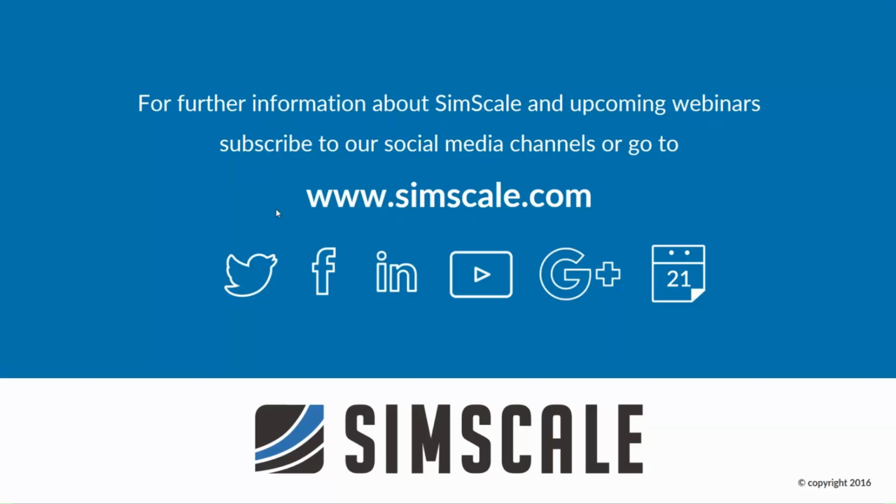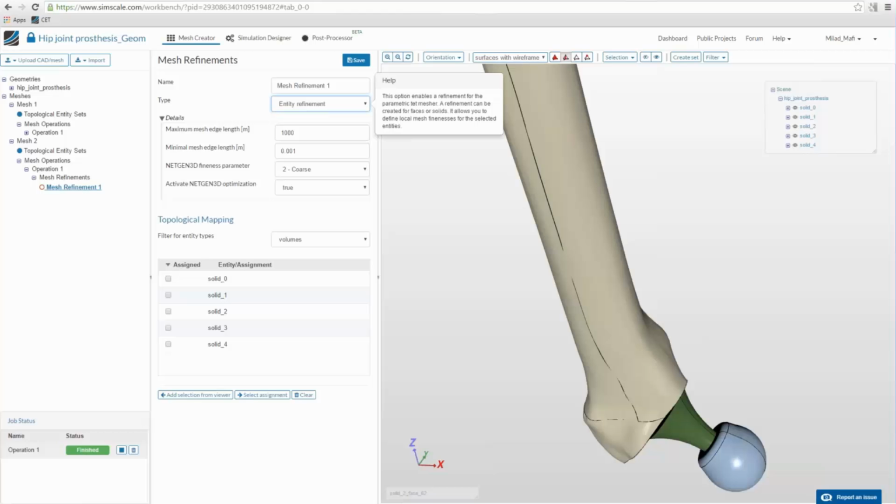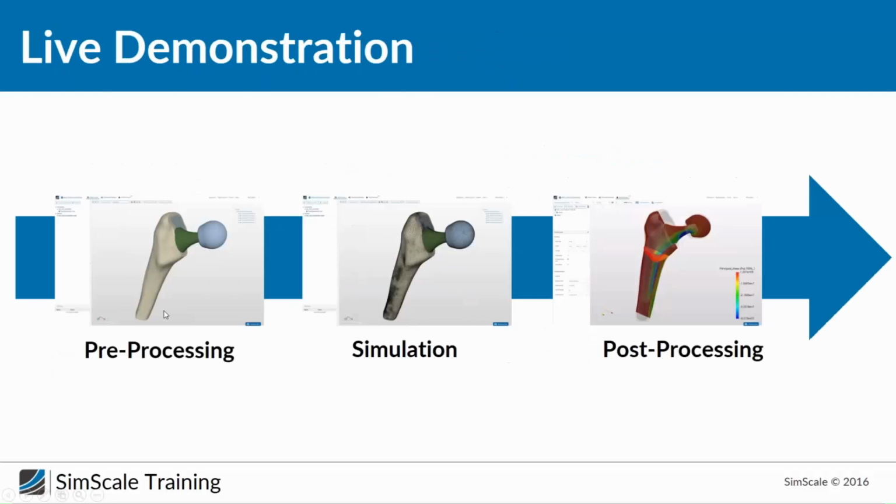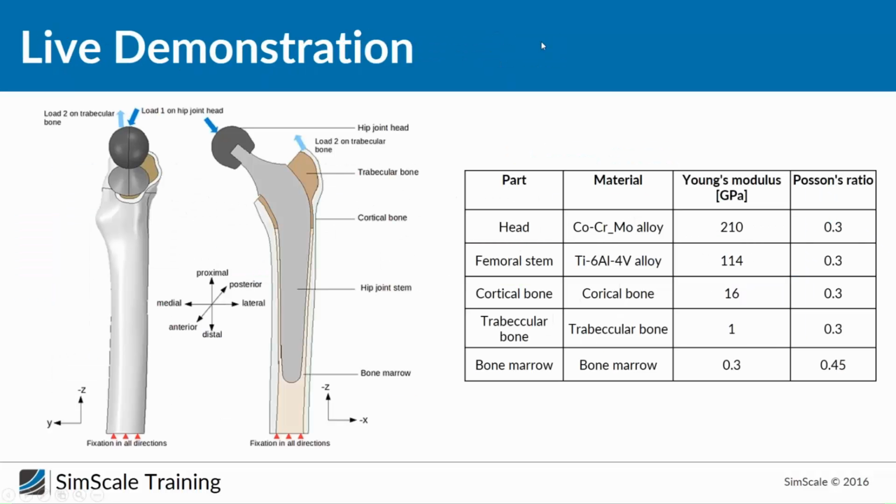Then Reshma wants to know if Young's modulus, Poisson ratio, and density are enough to characterize a material like a bone. That's a good question, and maybe therefore let's take a look back at our slides and take a look at the structure again of the bone. Basically, you can only describe a material by the 3 parameters if it has a linear elastic behavior, and if the behavior of the material is independent from the direction of the force. So a whole bone as a system you cannot model with just the 3 parameters.